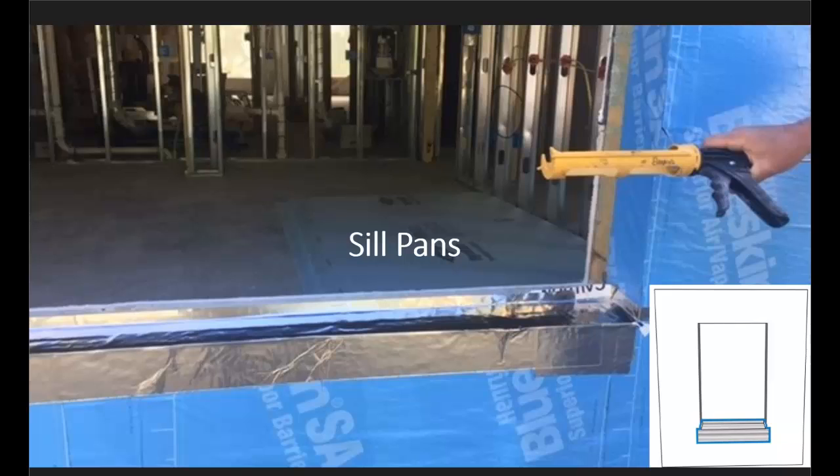Sill pans. If you have a project where a client understands the importance of protecting the underneath of our windows and doors, really cheap insurance here. I mean, you're talking $15 for a sill pan when these are where we put the holes in the wall, which is where it leaks. So it's thin, it doesn't build up in the corners, you can fold it, you can cut it, and right on site, it's going to fit in every opening. You don't have to worry about a preformed metal or plastic pan that's not going to fit.